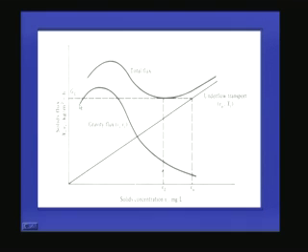Initially the concentration of the solids is relatively low, but the settling velocity, the gravity velocity, is high. So the flux, which is nothing but the product of concentration and velocity, will be relatively low here. But as the concentration increases, the reduction in the velocity is not so considerable compared to the increase in the concentration. So naturally the product will be high. That will continue to a certain extent, up to a particular value of Xi.